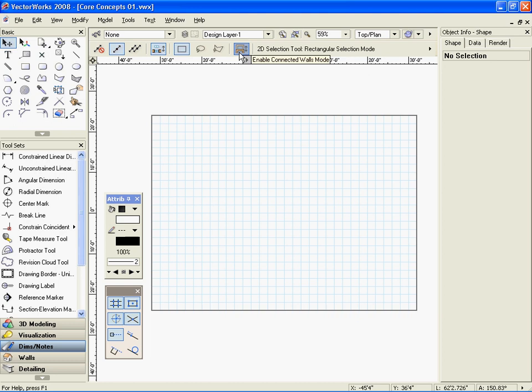drawing the object. While you can try all of these options and decide which suits you best, for the Vectorworks training CDs, the second option is used. Use floating data bar only when Tab key is pressed. This way, when you're drawing and need to set specific sizes for an object, just press Tab to activate the first field of the floating data bar, and then type in the size you need.